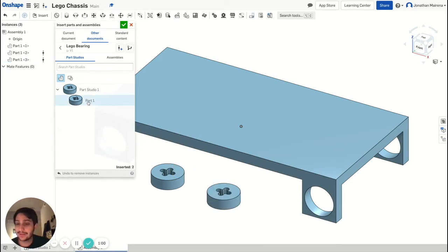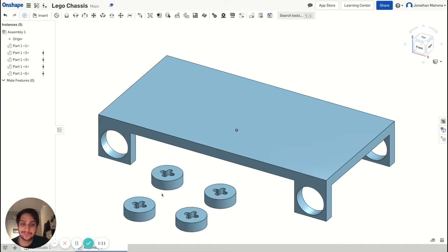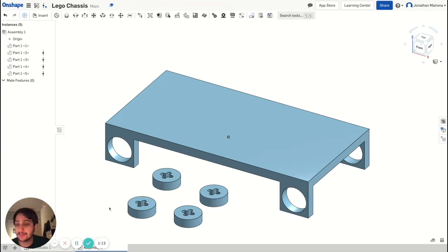You simply click on the part, then click on where you want to put it. Then click the check when you're done. Now we're going to do our first mate. A mate is what makes 2 parts connect. You fasten them into place.